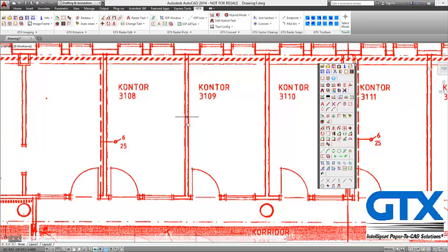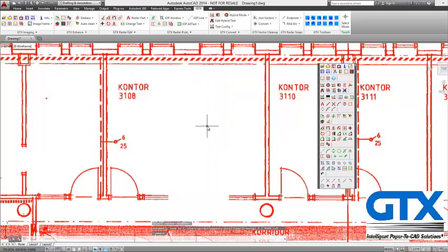So the first thing I want to do is erase the walls. So I use the erase raster command and I select the line option, and then all I do is draw over the line that I want to erase from the drawing. So I've selected the two walls. I then change it to window because I want to cut out the doorway, and I also want to take away the old room number. So they're all my three items that I want to remove from the drawing. When I'm happy, I hit return and they're erased.